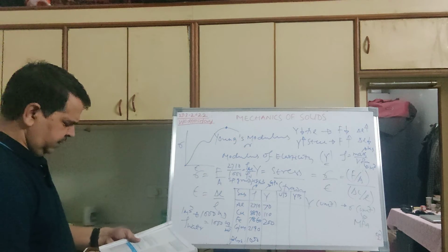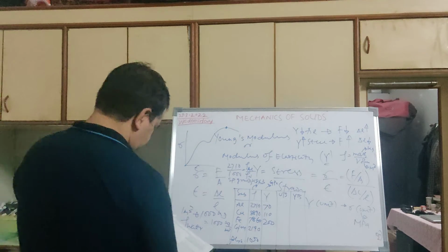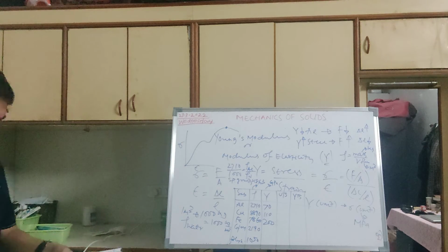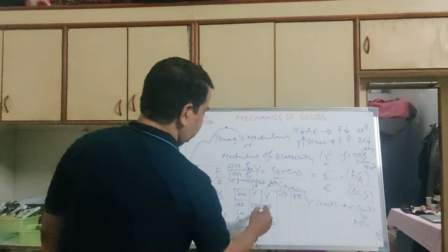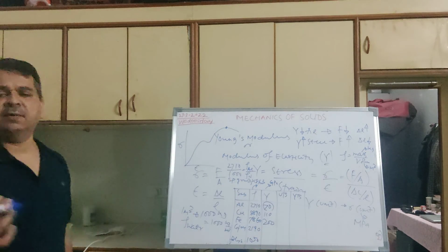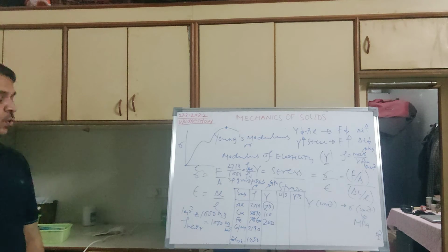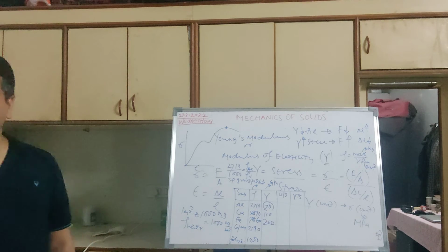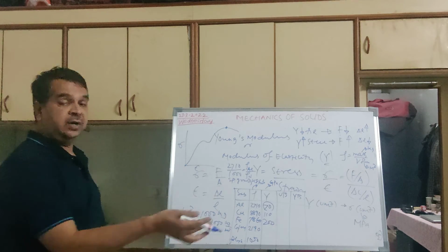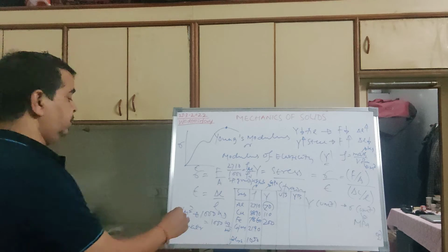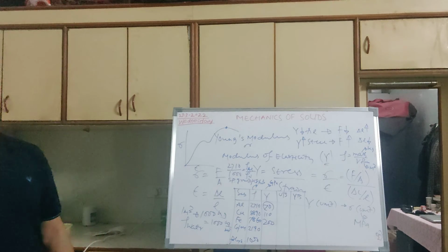Okay, so you can see here among all, iron will have lesser strength as compared to steel. Okay, iron will have 190. So iron and steel are different. Anyway, I'm not entering more into it. So just see aluminum is 70 gigapascal, whereas steel is 200 gigapascal. Gigapascal. So stress, when you come to strength, it will be in megapascal. But your Young's modulus will be in gigapascal.